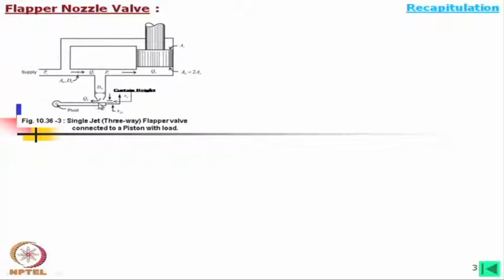In that case, basically it is allowing the oil to go to the ring end side of the piston, and while we are trying to control the motion of this piston, we are allowing the oil on the other hand side, but that flow we are controlling by the 3-way spool valve, isn't it?